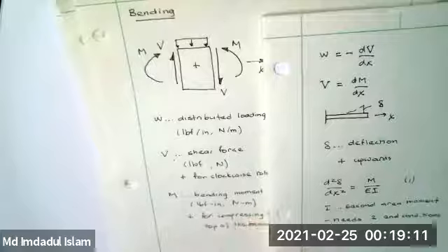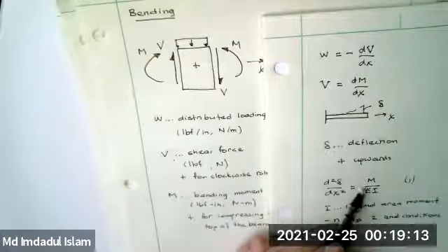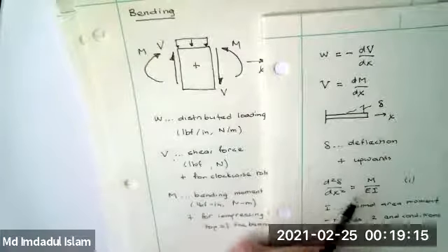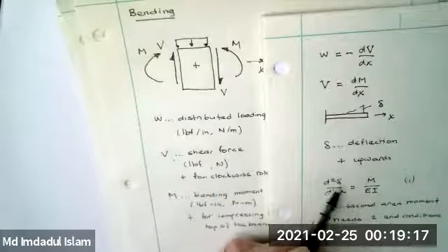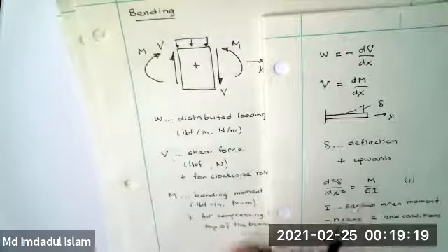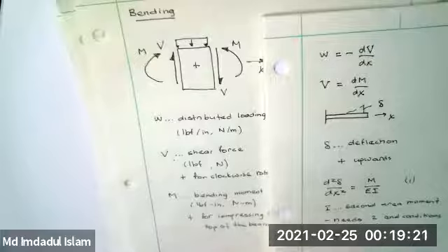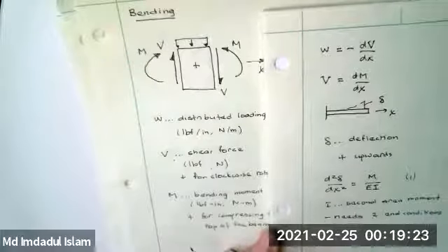Okay. You may have different M's for different parts of your beam. Every time you switch M, you'll switch this equation. Every time you have one of these equations, you need 2 end conditions. Some of these end conditions may be matching.